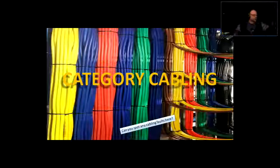Okay. So what is the problem with that? We can see here that there are some sort of zip ties being used for binding of those cables. If that were category 6A, that would be a big, huge no-no. All right.